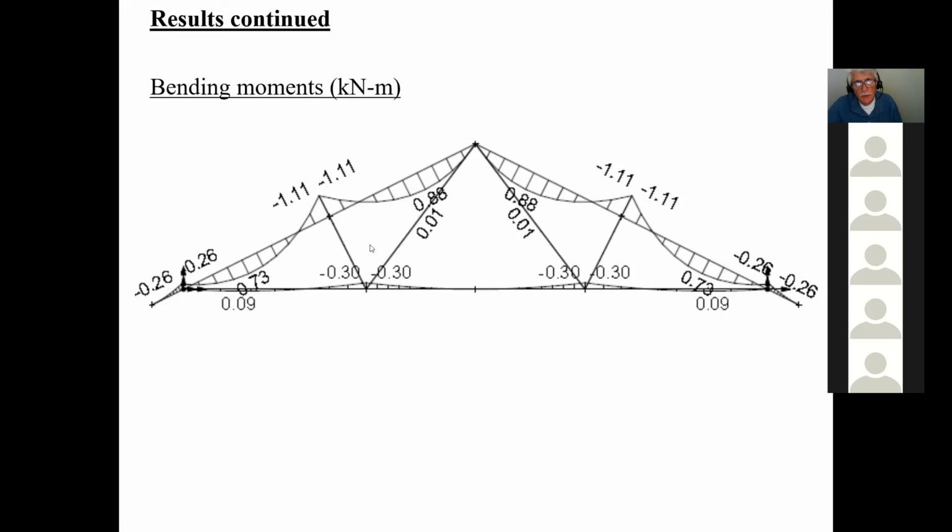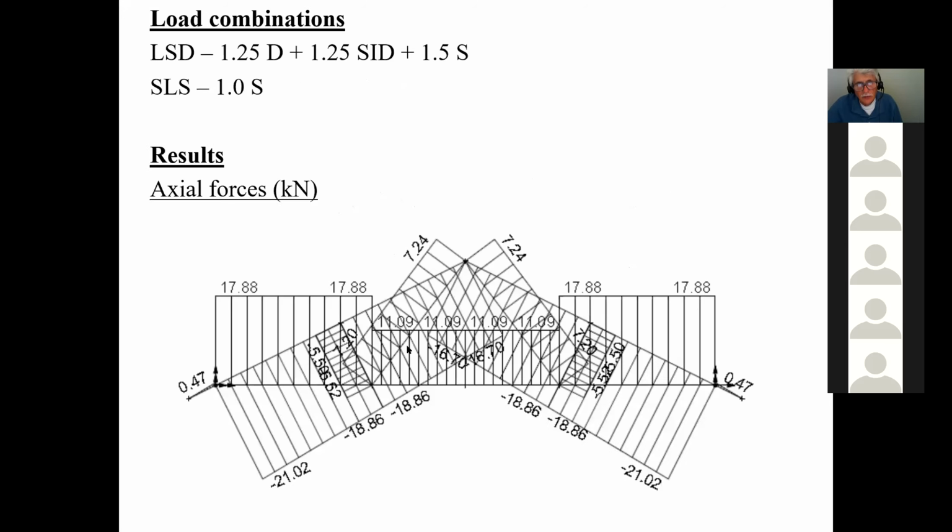And then on top of that, I still have to design these members here. This one's in compression. So therefore from AD, I will get the length of this. And then this, I have no choice but to calculate PR equal to phi, because I have no sheeting, I have nothing. I have to calculate what the PR value is, and make sure it's greater than the PF value that's in here.